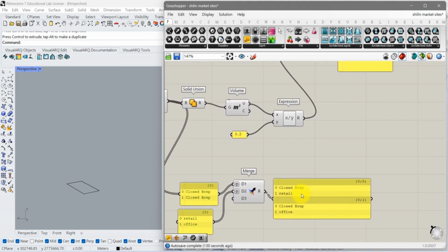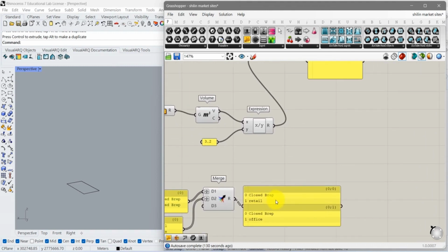So you get it? Now we can calculate how much floor area for retail, how much floor area for office building. If you go on, you can also estimate, for example, that you may need to have 20% circulation for retail spaces, or if it is more luxury or higher quality, maybe you take 25%, and this 25% of area is not for rent.